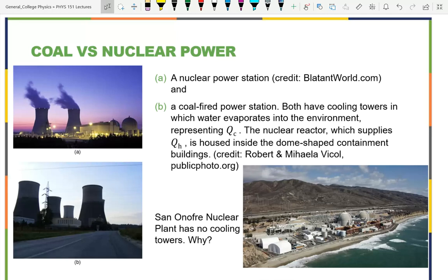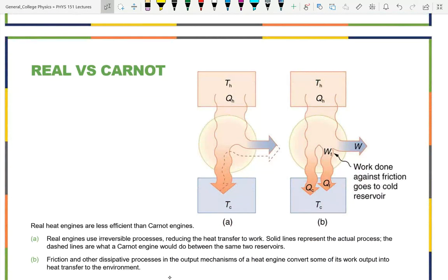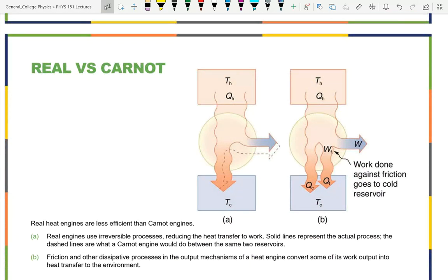Okay, I spent a lot of time on that slide, more than I intended, as always. I've already said the Carnot engine doesn't exist. Real engines don't reach the Carnot efficiency for design reasons as well as very simple reasons like friction. It's impossible to build something without friction, so that's going to always divert some of your work energy back into heat. So that is in addition to the second law saying you can't make a perfectly efficient engine. You have the reality of friction that makes it so you're not even going to reach the ideal efficiency.